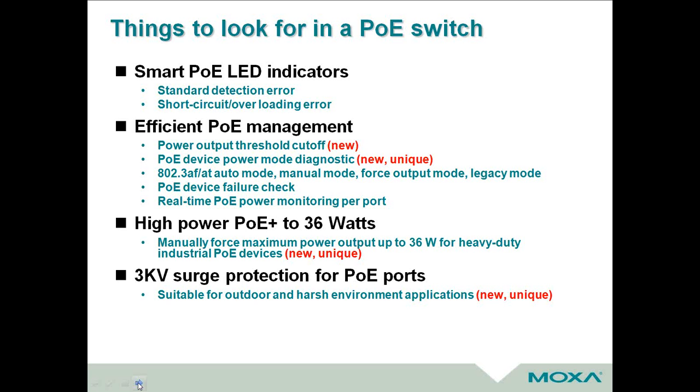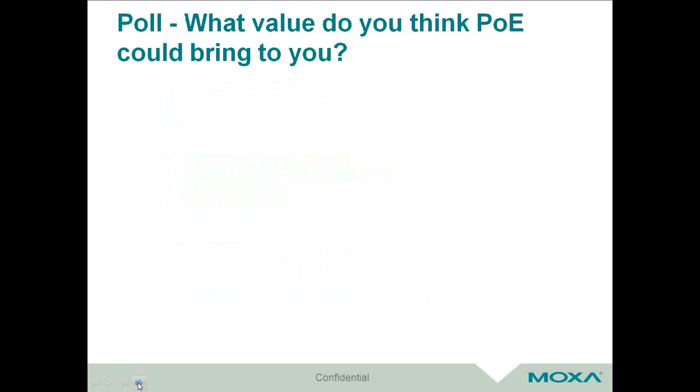Make sure it's got the right amount of surge for PoE, because PoE is power, and it does tend to fry the Ethernet ports if you're not using the appropriate surge protection. Unfortunately, not a lot of vendors use that. That's something that is somewhat unique to Moxa.